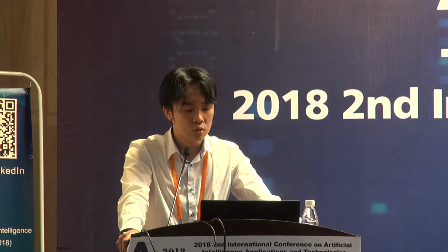And now I will describe the software design of my robot. The system software includes remote app software running on a remote cell phone and robot control app running on a cell phone on the robot side. Both apps are programmed with Java and are compiled and debugged in Android Studio 3.0.1 development environment. The robot control app can receive the command issued by a remote app and can send the running status of the robot, as well as monitoring video image to the remote app as well.